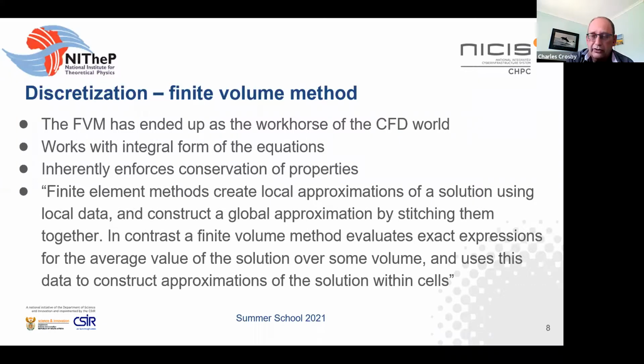If you find you've got a nasty problem set that is easily divergent, then you start finding ways of stabilizing it. And one way of stabilizing it is to run it first order first. And then when everything is nicely settled down, then you switch to second order. If you switch to second order too soon, it'll blow up. If you switch to second order too late, it'll just take longer.